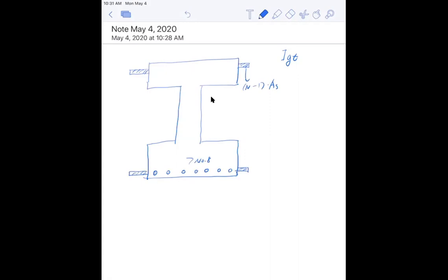Now remember for tension, as we said before, when it's cracked, you do nA_s directly. But this is for gross, this is total, which means this is uncracked. When it's uncracked, you convert everything. So again, you have to fill back in the reinforcement, and this is (n minus 1) A_s. Be careful, this is uncracked, so you have the entire section to work with.